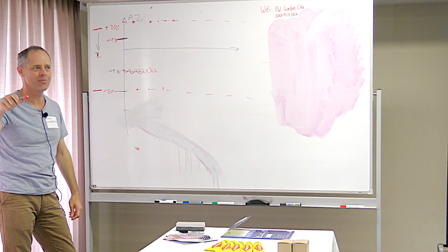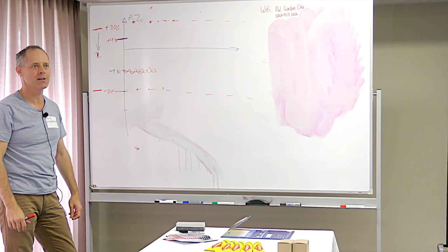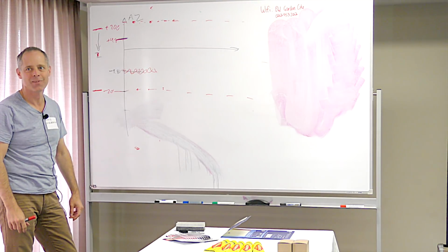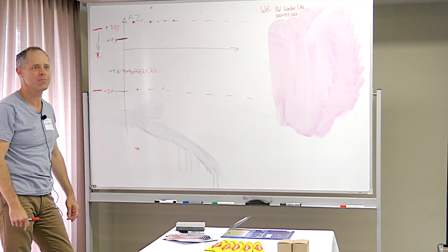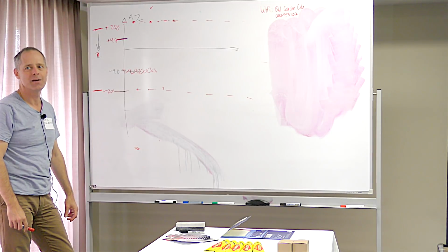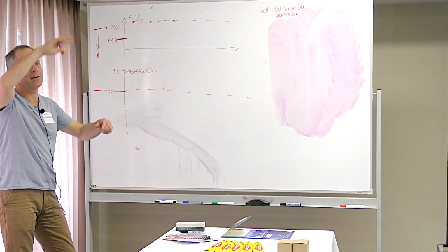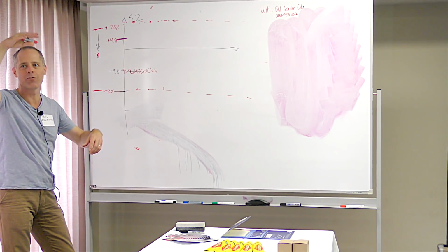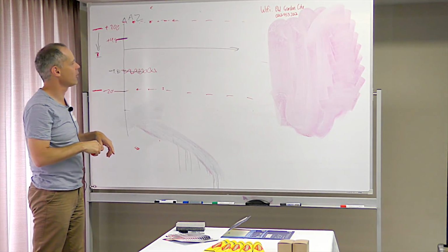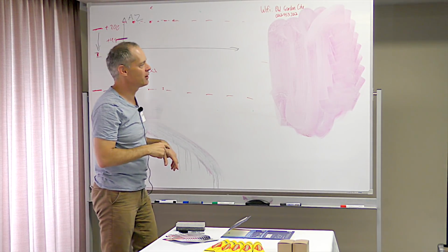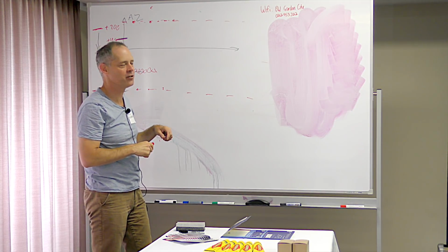The height control loop ramps up to full throttle, trying to stop it free falling, which immediately makes the vibration worse, and the copter accelerates into the air very rapidly. Now, eventually the EKF will do a reset, and then it'll come down again, and then it'll keep repeating the process over and over again. And that's what we see in this log here. Now, fortunately, this vehicle was not in a mode where it was using height, or else it would have been a very interesting flight.